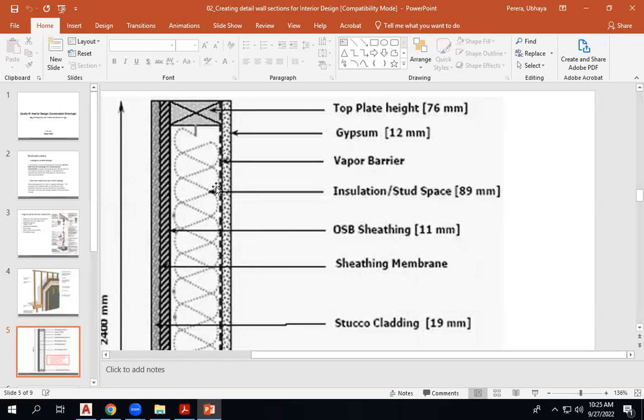What do you say? Shall we go with the concrete wall at the bottom, the ground, the first floor level to the second floor level with the concrete, and the top part will be brick. In the detail you can see, you cannot have timber in the ground level and have brick on top, because the load of the brick wall cannot be taken by the timber. So shall we go with the detail that I have given you, the 3 sections I have got? We'll follow that one into our drawing.